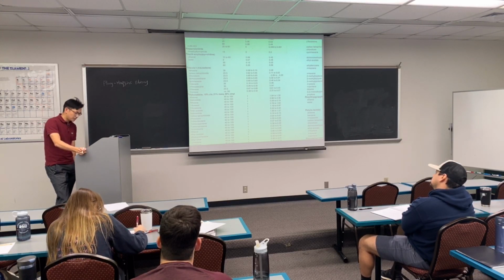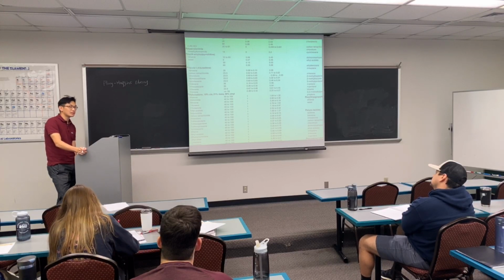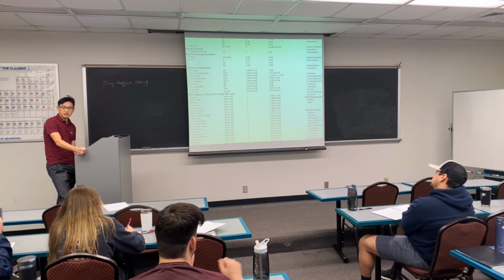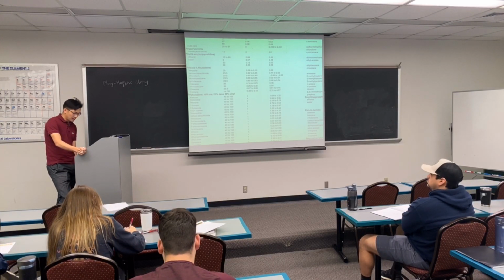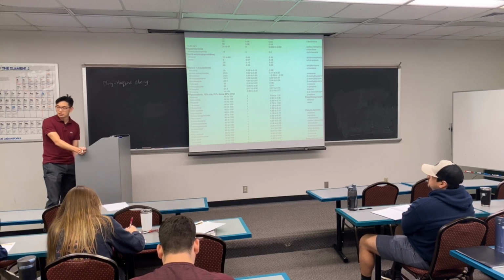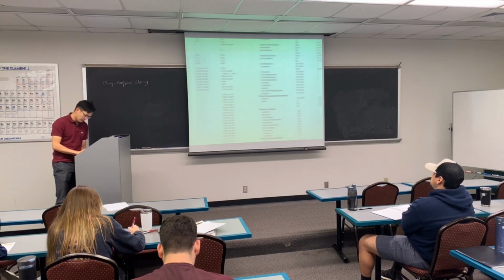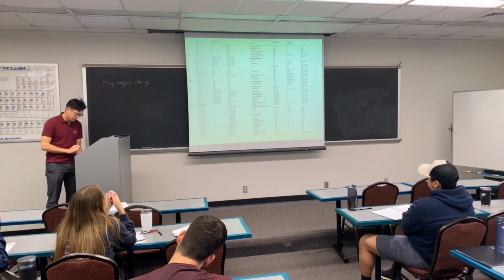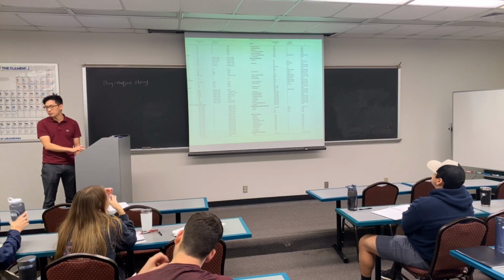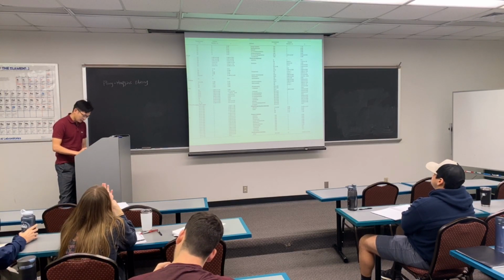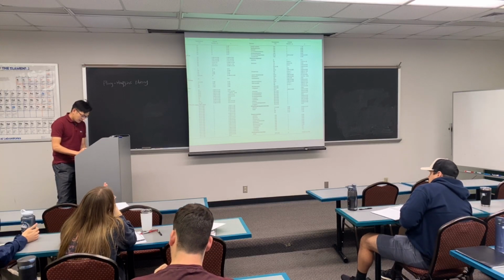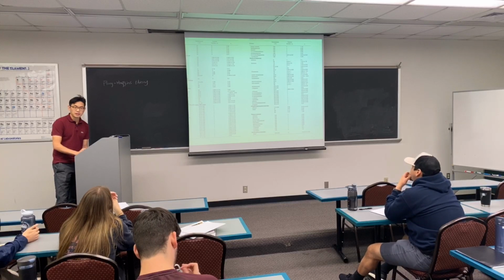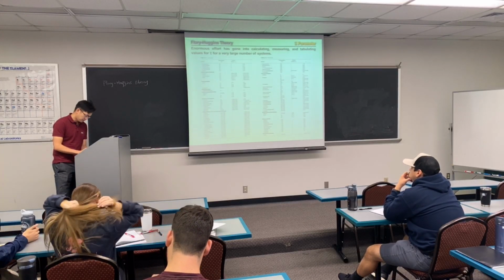Relatively speaking, the larger chi is, the more unfavorable the interaction. On a relative scale, chi is typically on the order of 1, up to 4 or 5 is possible, but most are single digits, between 0 and 1. This is an example that everybody can look up: what is exactly a chi value? This mostly lists polymer-solvent. So when you need to look at polymer-polymer, you need to do one layer of conversion. Okay?